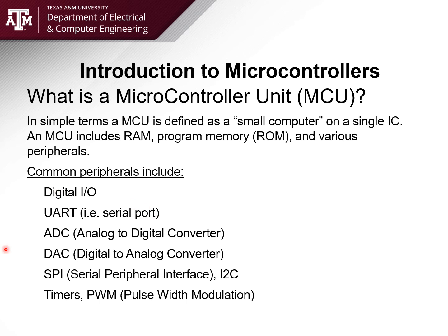And then obviously there are devices dealing with the analog world, because in the end, sensors are usually analog devices, and so you need to get that information into the microcontroller to make an intelligent decision that you can do programmatically. You do that by using an analog to digital converter, ADC for short, and there are different resolutions and different speeds, but ADCs are quite common as a peripheral built into the single IC of a microcontroller.